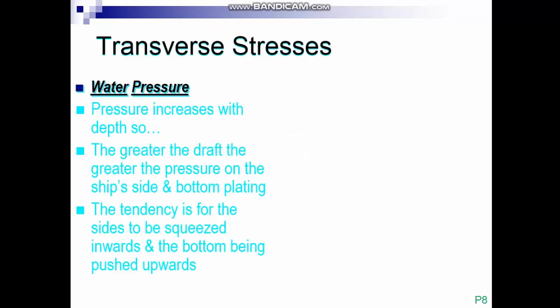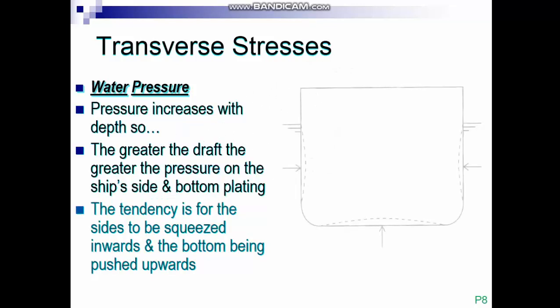Let's talk about transverse stress. First of all is water pressure. Pressure increases with depth, so the greater the draft, the greater the pressure on the ship's side and bottom plating. As you see here, this is a ship, so the water is all around the ship.